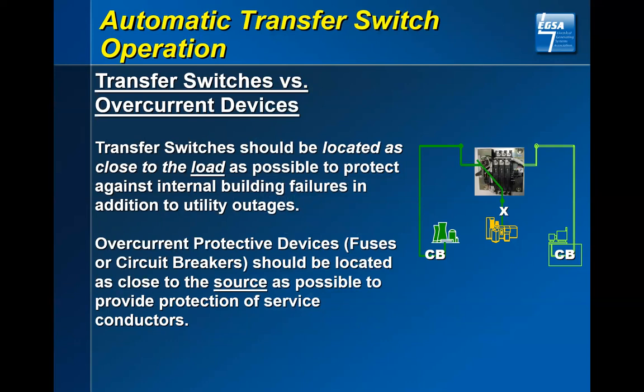In the case of a circuit breaker, you may be connected for anywhere from 3 and nowadays all the way out to 30 cycles. Transfer switches of a certain manufacturing design, several manufacturers offer those, are capable of withstanding a fault all the way out to 30 cycles. A half second, that's an eternity in the electrical world.